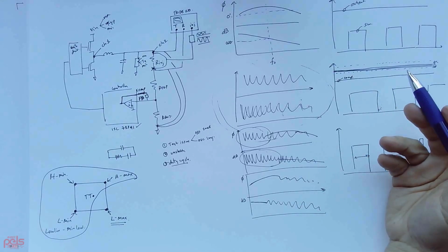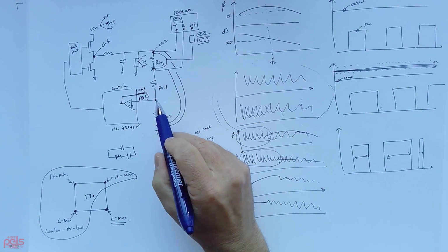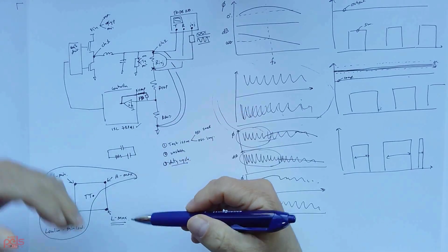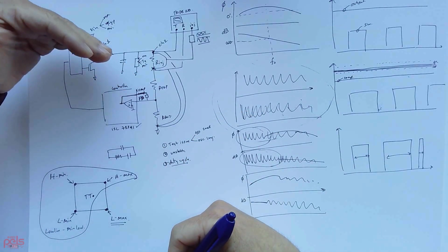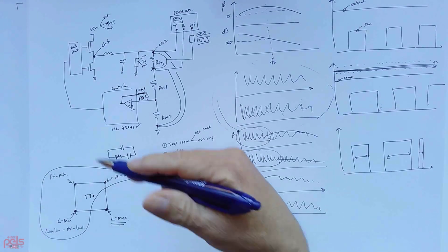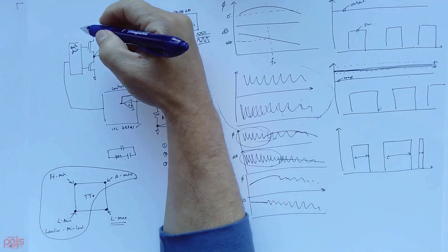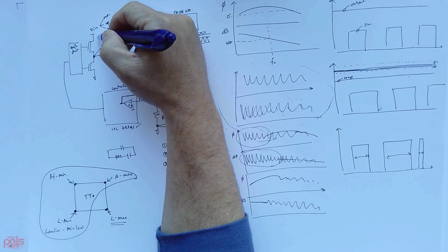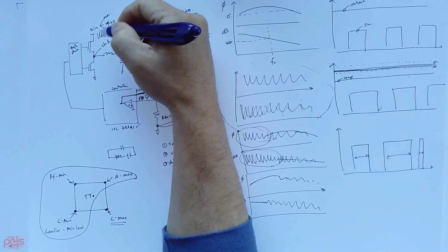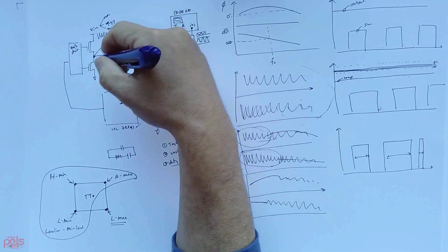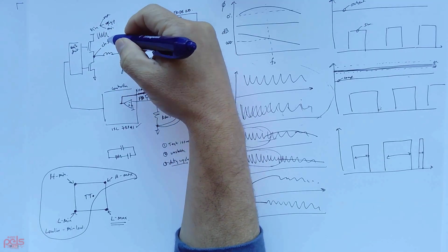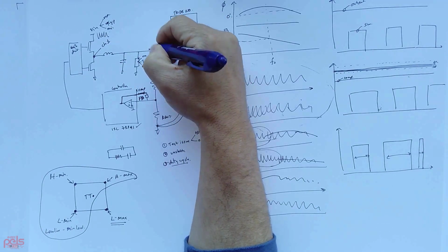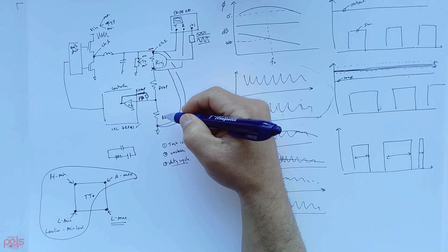Why am I not able to get one? Well, because my power supply is now running open loop. And the implication of that is that I am not benefiting from negative feedback. So if the input voltage to my converter has wiggles in it or noise, the negative feedback in the power supply attenuates that noise, so that now is going to become so many dBs less at the output, right?